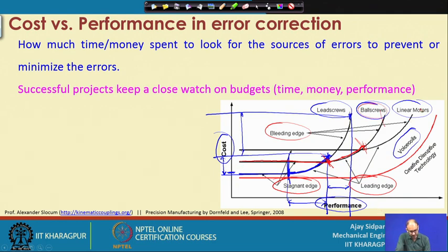If you continue with the linear motor, because here the sophistication in terms of the motion controller is increasing in this direction. So, these are the linear motors. That is more important, because we are getting micron or nano level of resolution when moving. But if you see, cost is also increasing continuously. So, this is more costly, but you can get more performance without any extra cost.